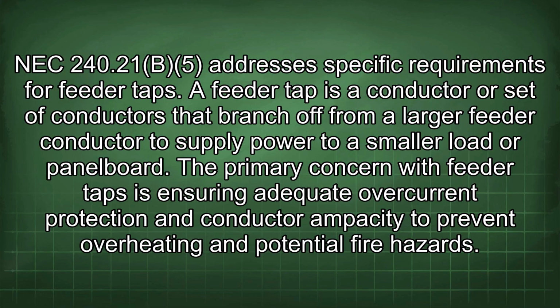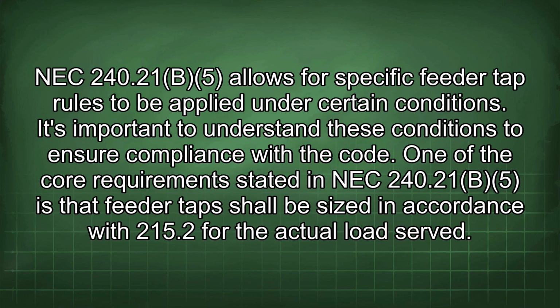The primary concern with feeder taps is ensuring adequate overcurrent protection and conductor ampacity to prevent overheating and potential fire hazards. NEC 240.21(B)(5) allows for specific feeder tap rules to be applied under certain conditions. It's important to understand these conditions to ensure compliance with the code.